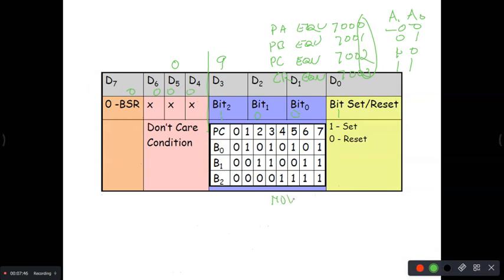You move the control word to the AL register. What is the control word for this? 09H. Move the control word to the AL register. Now, what is the syntax? Come on, tell me. OUT, AL, which port? Can you tell me the instruction now? OUT, AL, comma. Is the syntax correct?